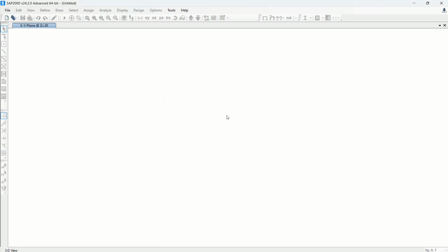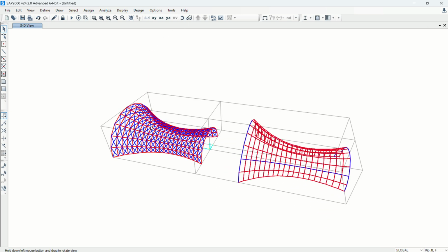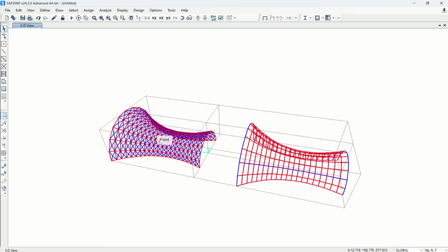the surface together. All right, so you see that all the reference geometry I brought in. There is actually something I wish I could do separately, because in order to assign the section property I need to select, but there are too many elements, so sometimes it's cumbersome to click and assign the section properties. So if you have a bunch of primary elements and diagonals, maybe I could export them separately, diagonal members and primary members.